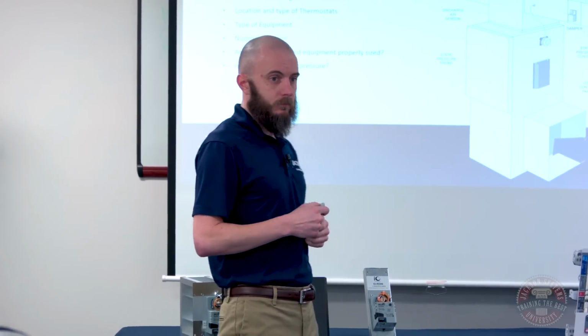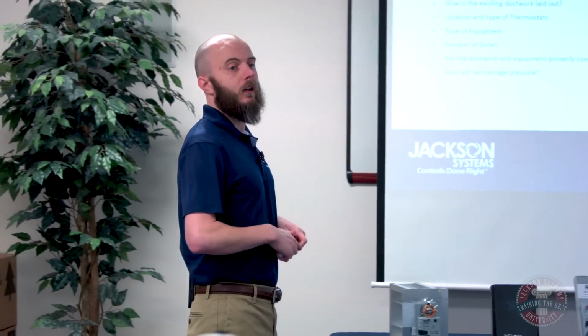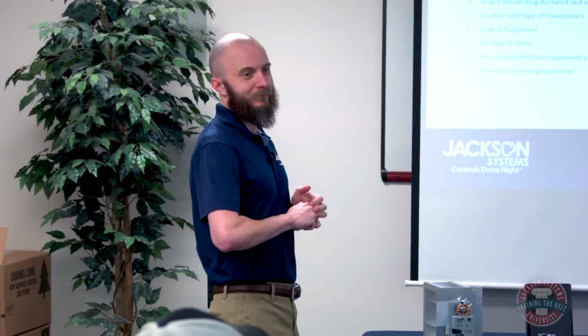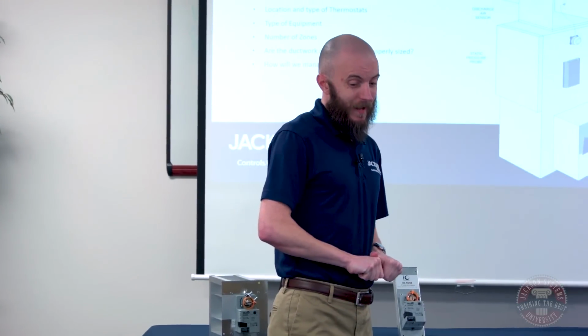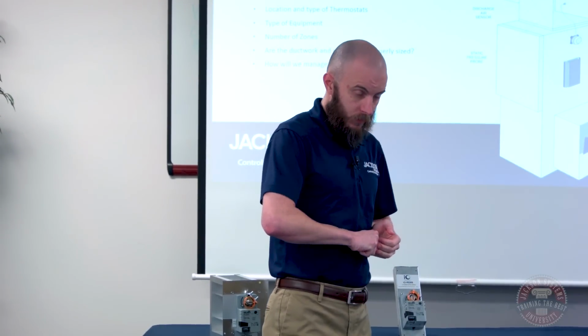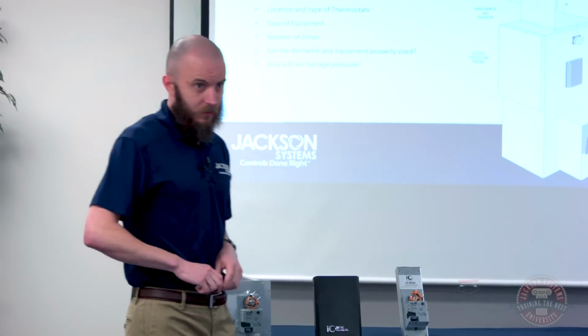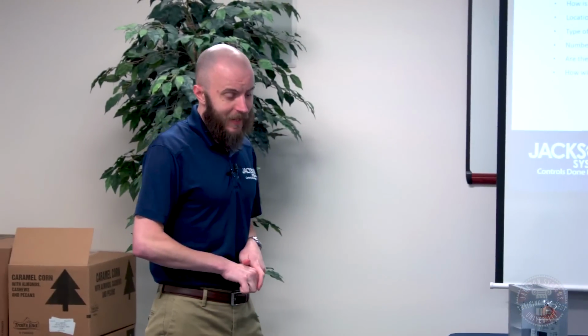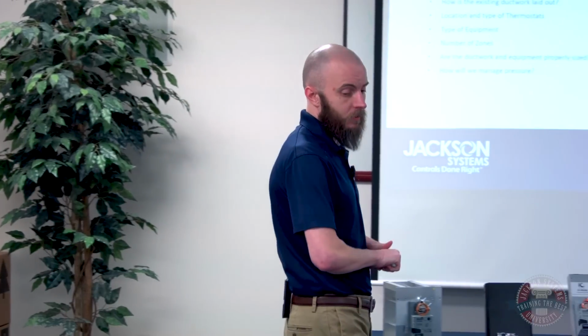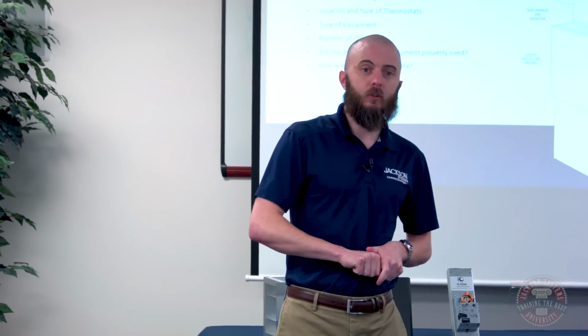You have a question? Okay. Ferris asked if he will need a C-wire if you use a Wi-Fi thermostat for the zoning area. For most zone panels, you probably will. And I'll talk about thermostats here in a minute a little bit more, but yes, you can use Wi-Fi thermostats with most zone panels. And in most cases, yes, you will need a C-wire, a common wire.